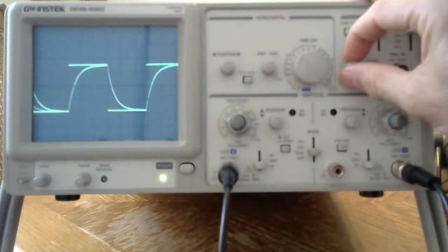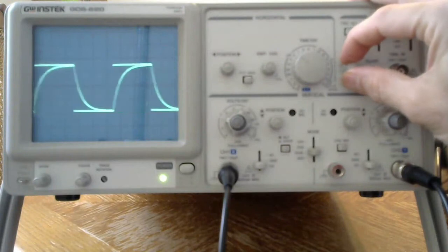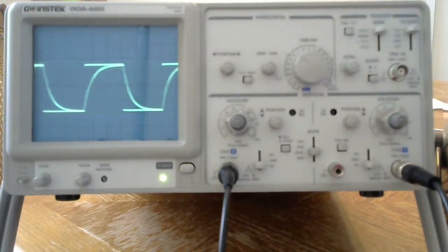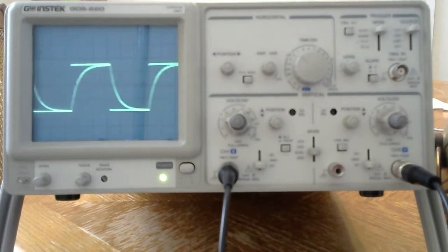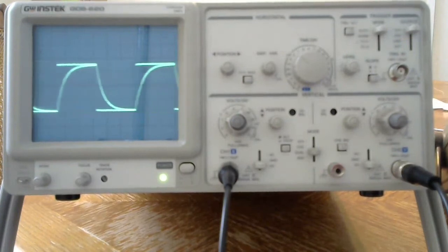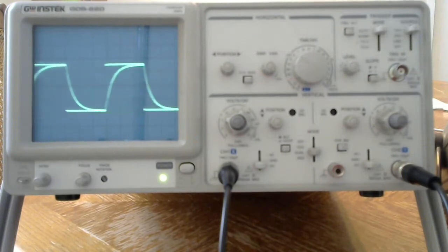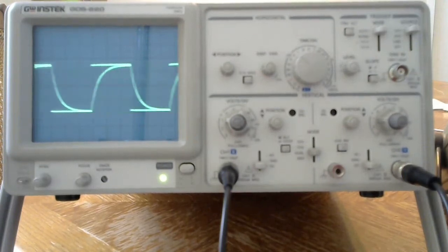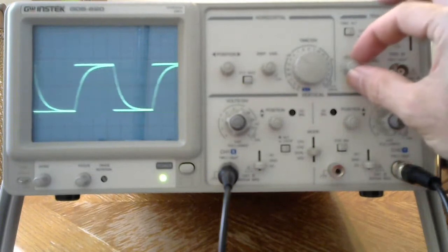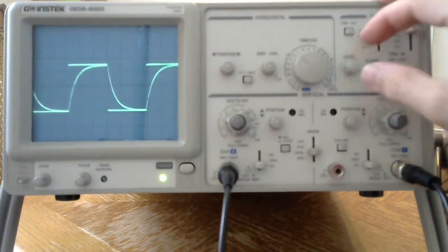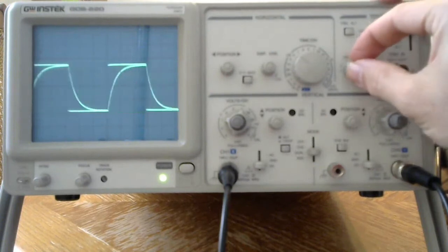And if I change where that happens, notice that things start to drift, because in this case I'm restarting my time sweep at a different rate than my signal up and down is changing, so the signal scrolls down. So I can change the level, look for a particular time at which you reach a particular value and restart my sweep and find a stable signal.